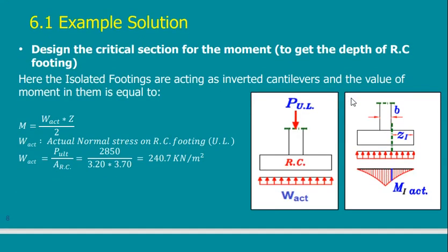Now we shift to the other part of the design, which is design of the thickness of the footing and the reinforcement. I will go to the concrete code. Then I will use the ultimate load, and I will start my design. So in this case, I take the ultimate load, I divide it now by the area of the footing.